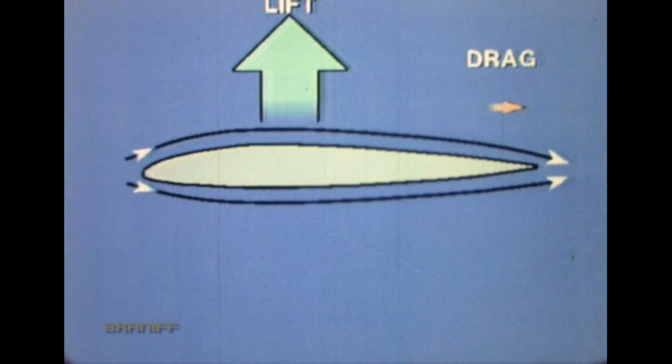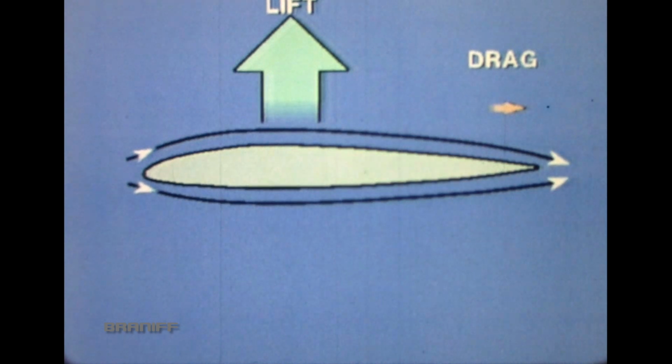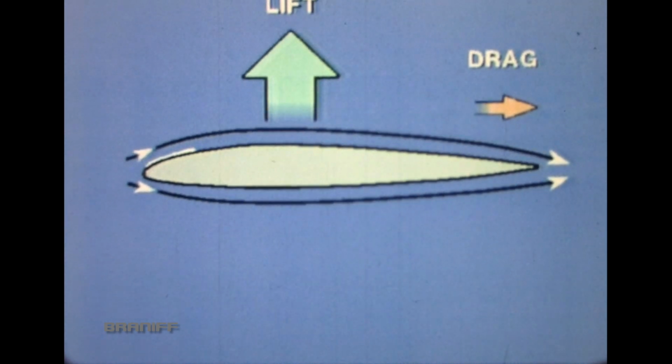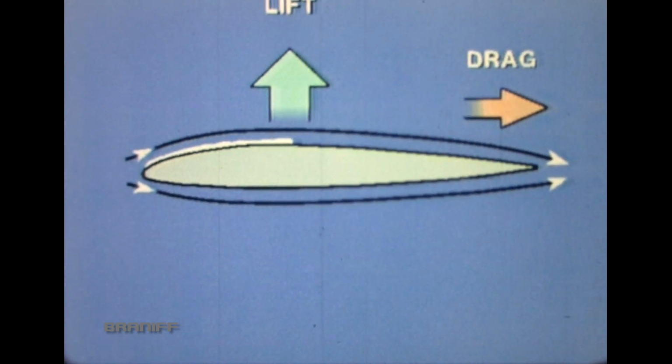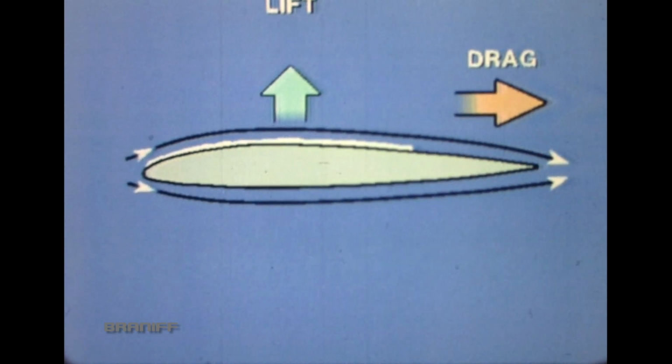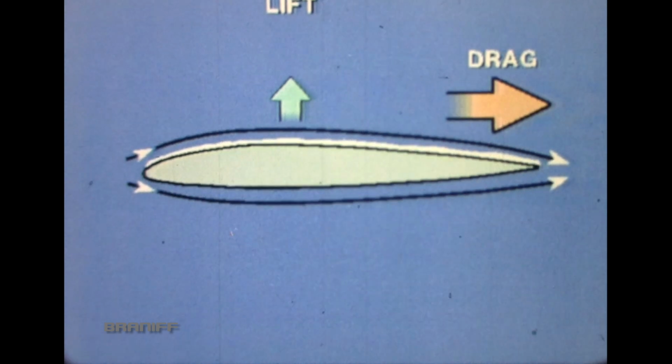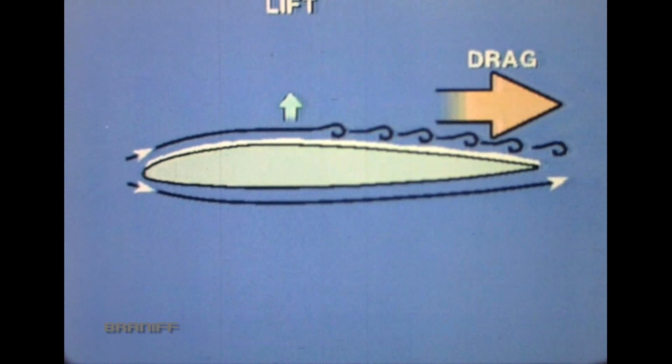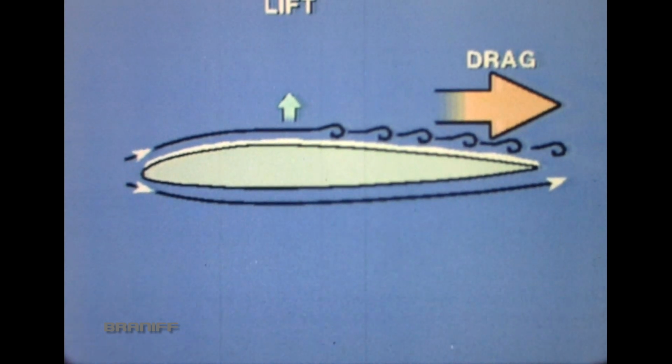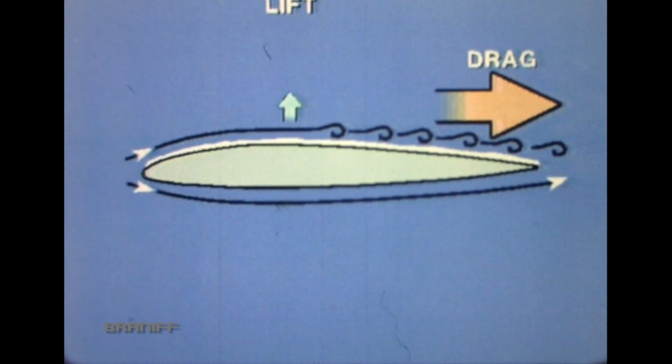Certified performance speeds are determined using an airplane with smooth, clean surfaces. Surface contaminants such as ice, frost, and snow cause airflow disturbances which adversely affect the lifting capability of the wings. The horizontal and vertical tail surfaces are also affected. At the same time, the contaminants increase drag. The effect varies depending on the degree and location of the contamination.